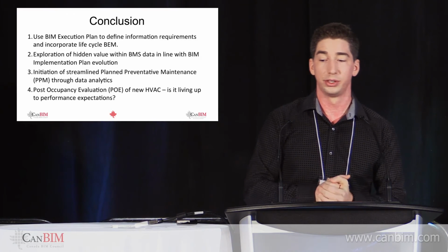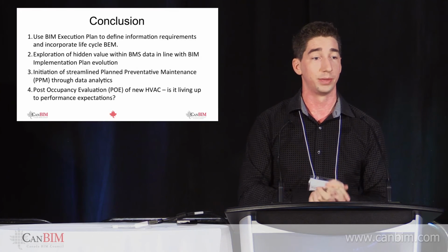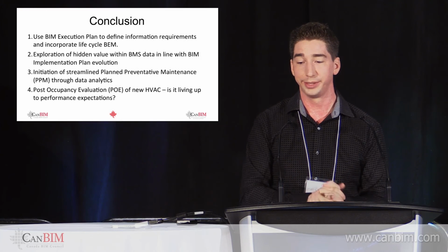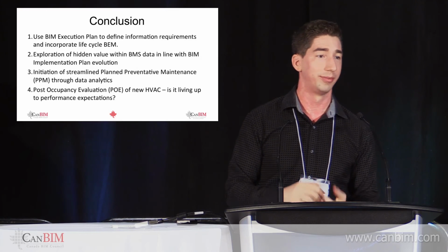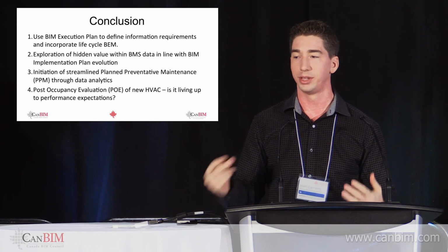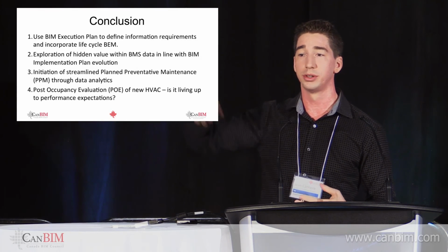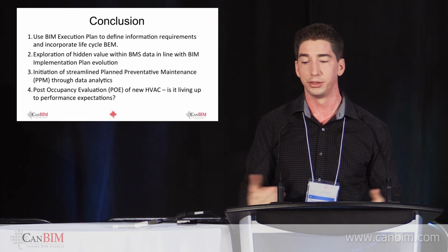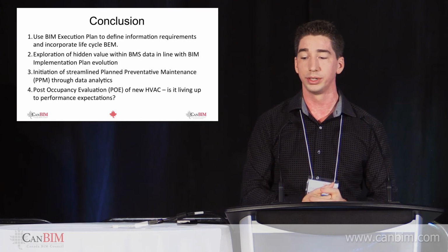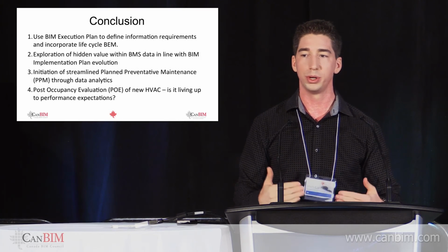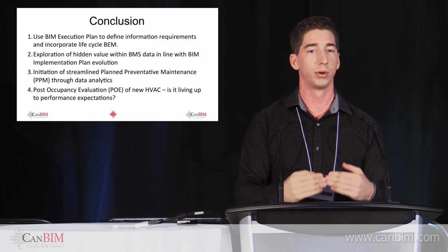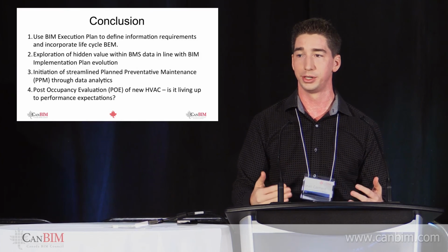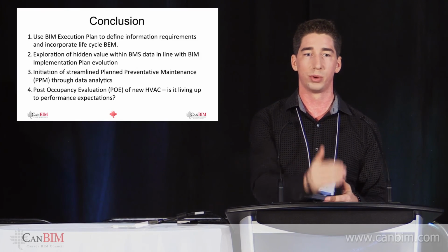We can also start to explore the hidden values in the building management systems, in line with the implementation plan. We can plan preventative maintenance. If you know that when your set points reach a certain temperature something happens, you can start to trigger these settings. And finally, you can do a post-occupancy evaluation to see exactly how it works. The idea is to push the energy model a little past code compliance into enhanced commissioning, so you can commission using model-based commissioning. That's the next stage we're trying to push into.